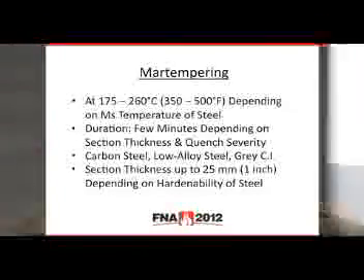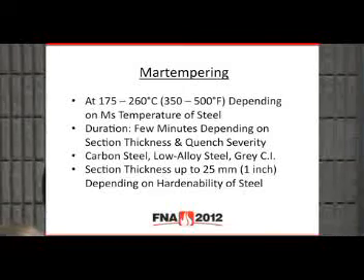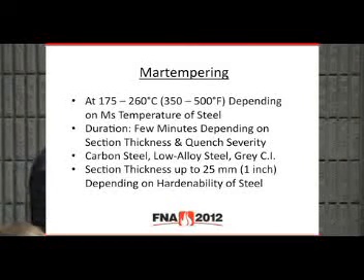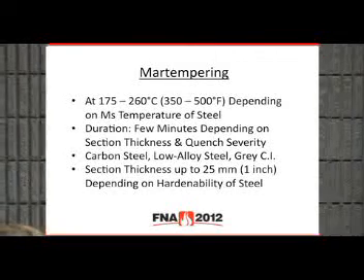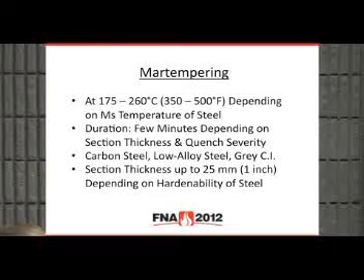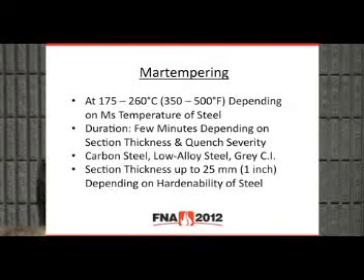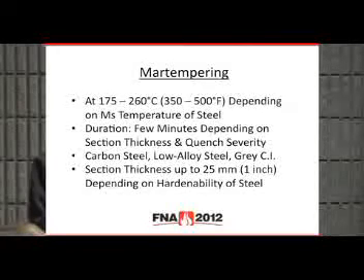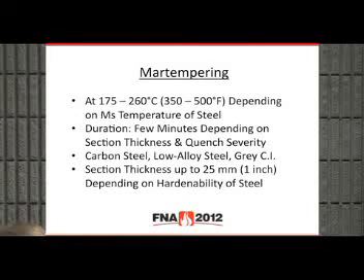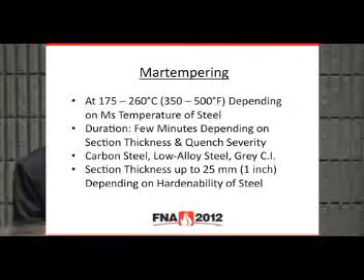In martempering, the salt temperature is usually in the 350 to 500 degrees F range, depending on the type of the steel. And the duration, that means how long you keep it in the salt bath, is usually a few minutes depending on the section thickness and the quenching severity. It's applicable to carbon steel, low alloy steel, gray cast iron, etc. And section thickness up to 1 inch can be martempered depending upon the hardenability of the steel.